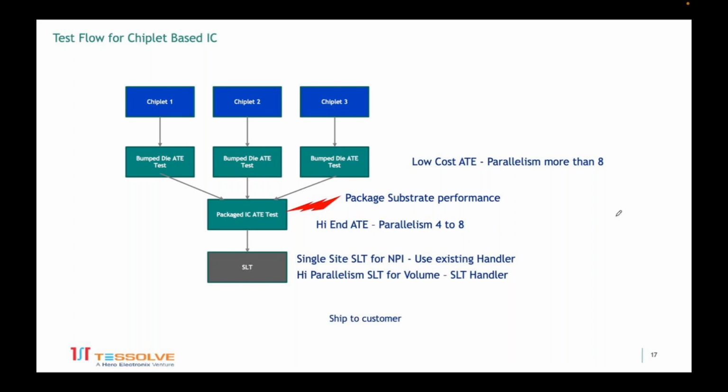And there are customers, we have seen, who even after SLT want to do some confidence building. They do some basic tests, one more pass in an AT, maybe a low-spec AT, doing some continuity and shorts tests, just to ensure that SLT, after finishing everything, has not spoiled the device or caused some basic issues. So they do some more tests if required.